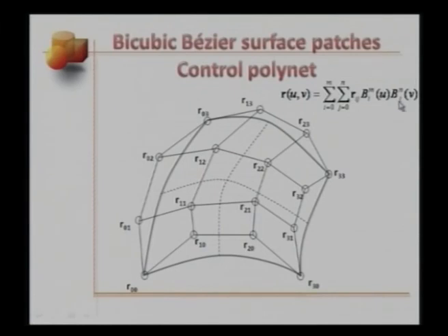Since the bicubic Bézier patch, or any Bézier patch for that matter, is derived from the corresponding Bézier curve models by use of Bernstein polynomials, all the associated properties get inherited. From the design viewpoint, this means that this patch will be lying within the convex hull defined by this control net. Also, the overall shape of this patch will be controlled loosely by the shape of the net.